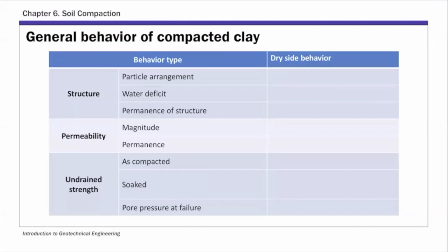So for structure, if you're compacting soil on the dry side, particle arrangement is more random, and you have more water deficiency. And the structure is more sensitive.